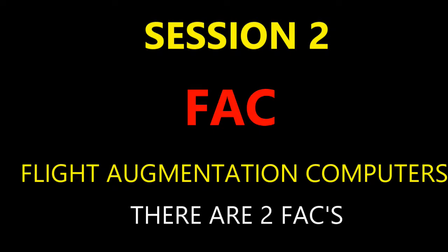So I just gave you an idea of the yaw damper function. And so what do we have in relation to this? Basically, when you have both dampers engaged, channel 1, yaw damper 1, is going to be the main one. That's going to be running first, or active, if you will. And then the second one is going to be synchronized on the position of yaw damper 1. Okay.